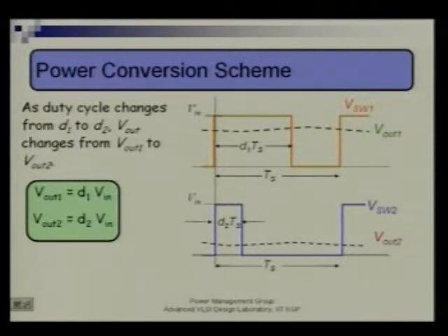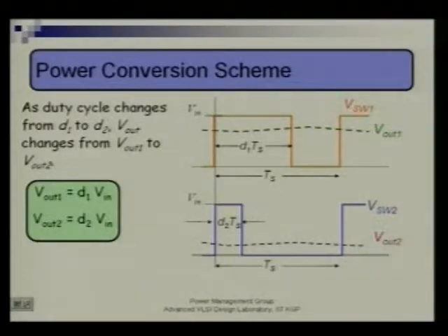Now, why do we need to consider volt second balance at all? Here we can straight away, through averaging, say that our output is this much. But there may be other topologies in which taking a switching signal and averaging, this kind of simplistic technique, might not be easily applicable. I'll show this slowly. Hence you should also learn about volt second balance. This averaging is the rudimentary, crude way of getting the output voltage, and when you apply volt second balance, that will be the engineer's way of getting the output. That will help you solve a wide class of circuits.